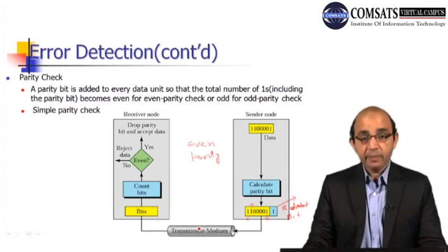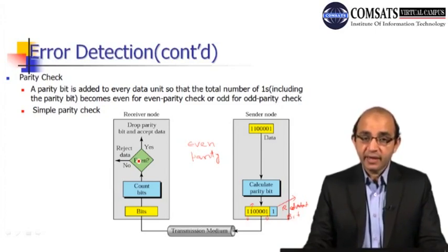So I have mentioned most of the scenarios by taking this parity check as an error detection scheme. So transmission medium, right, channel, and then the bits have been received, and here we will be performing the check. This is the parity generator, and here the parity check. So here we have to decide whether the data is correct or incorrect. As mentioned, this parity check will not detect an error if we have errors in 2 bits.